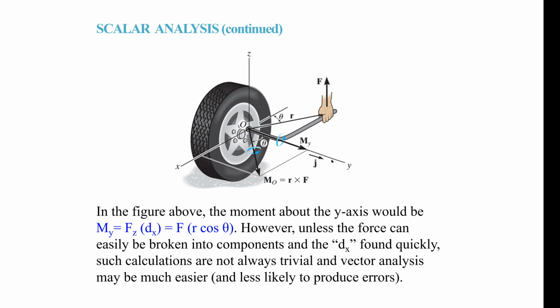In this case, it would be y, right? It's not really about a point. You're more concerned about what is the torque, or what is the moment about an axis or a line of action. Okay, and in this case, the line of action would be along y, right? And the real point of this is what amount of this torque is used to actually either tighten or loosen this bolt or this nut.